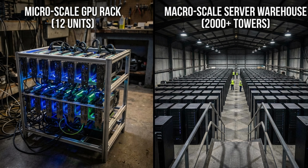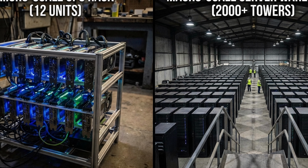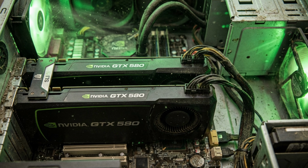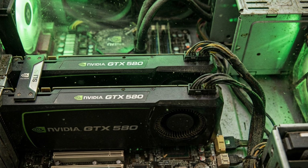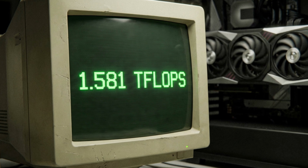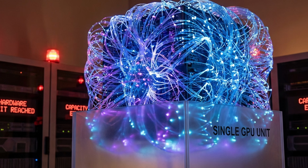Research from the era demonstrated that just 12 modern graphics processors could deliver the deep learning computational performance of 2,000 traditional central processors. To train the massive AlexNet model, the developers utilized 2 NVIDIA GTX 580 consumer graphics cards, each costing roughly $500 and equipped with 3 GB of video memory. These specific chips had a theoretical performance of 1.581 teraflops in standard floating point precision. However, the model's sheer size exceeded the memory capacity of a single chip.